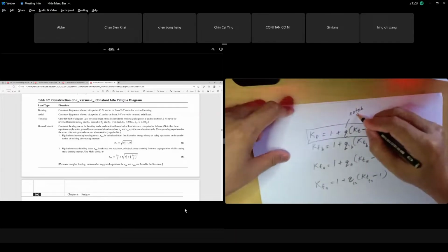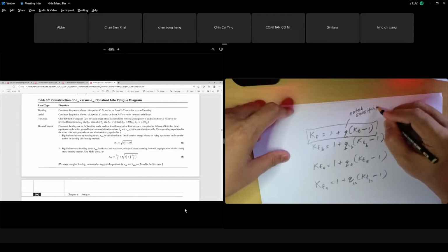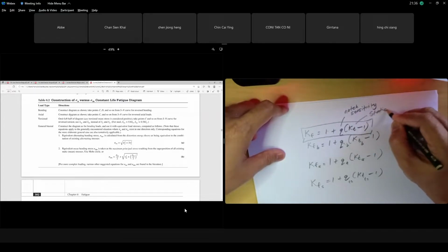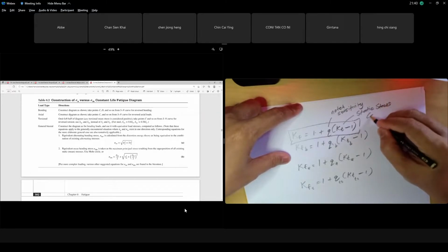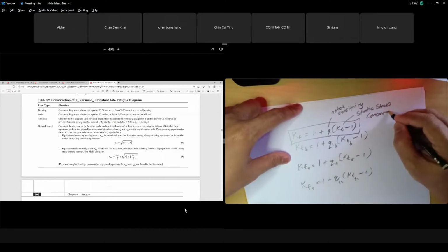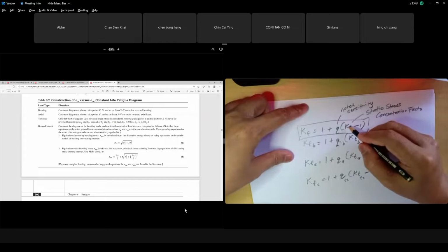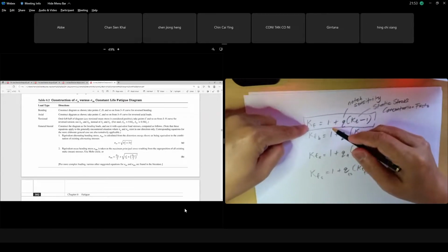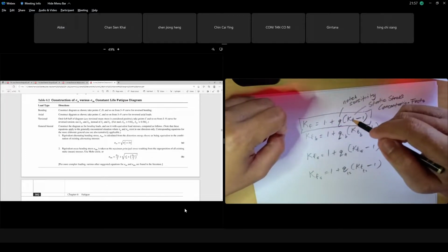I will show you a little bit in our sample. Notch sensitivity. And Kt is your static stress concentration factor. Because now we go for fatigue, what we find first is the static stress concentration factor, but we have to minus 1, times q, plus 1, and we get the fatigue stress concentration factor. We adjust to the fatigue stress concentration factor. Okay, I hope you understand.